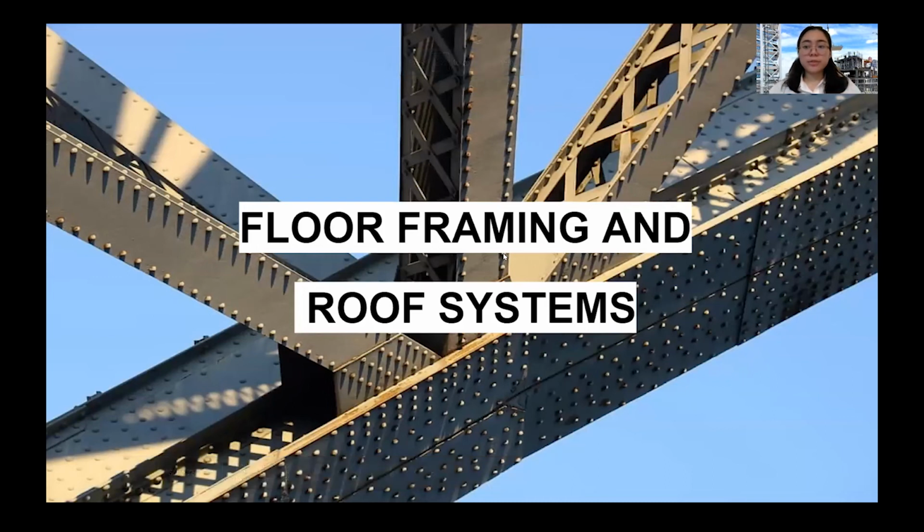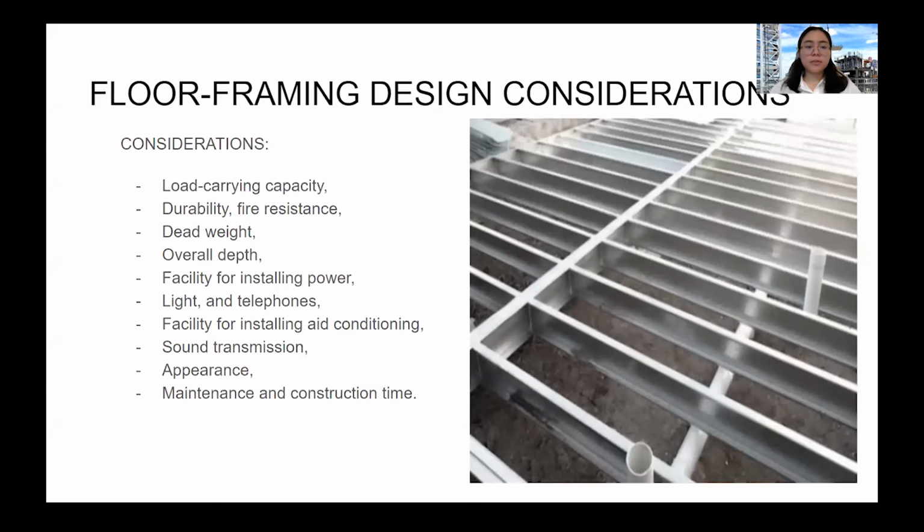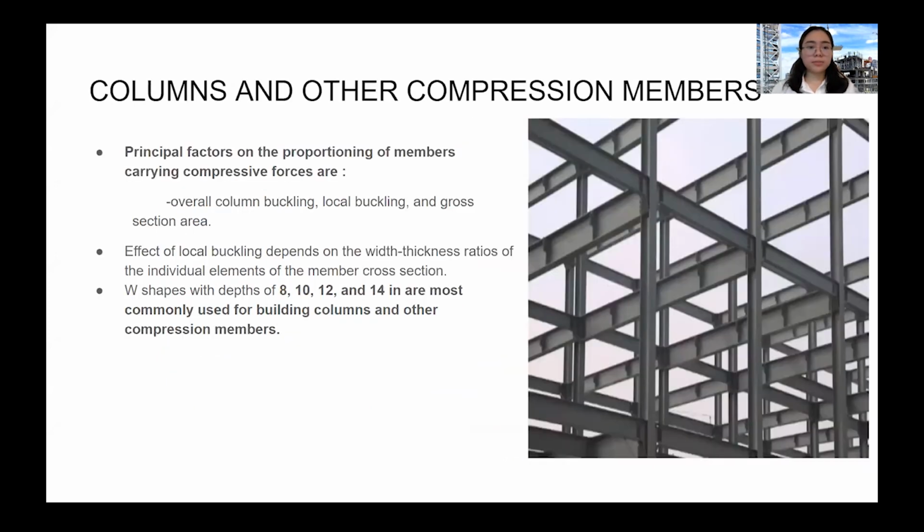Floor framing and roof systems. Floor framing design and considerations: load carrying capacity, durability, fire resistance, dead weight, overall depth, facility for installing power, facility for installing air conditioning, sound transmission, and maintenance and construction time.